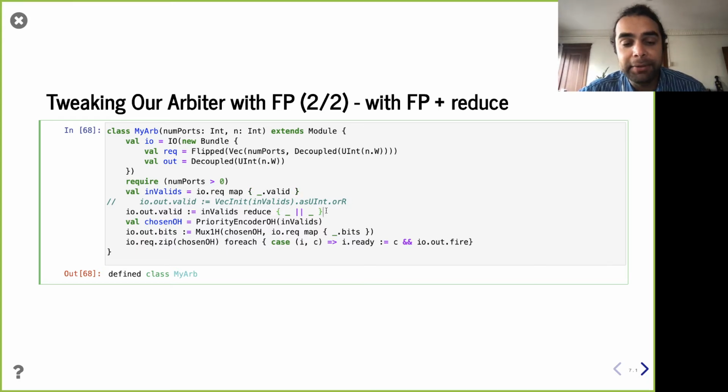And interestingly, when you think about what that means mathematically, if I have n bits coming in and do an OR reduction, it gets down to 1 bit. That 1 bit is going to be true if any one of the input bits is true, and the output bit is only going to be 0 if all of them are 0, right? So basically you could turn an OR reduction into a comparison against 0, where if it does not equal 0, then it's a 1. If it does equal 0, it's a 0. Mathematically, that's a way to think about a reduction, right?